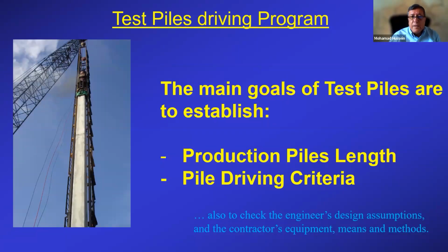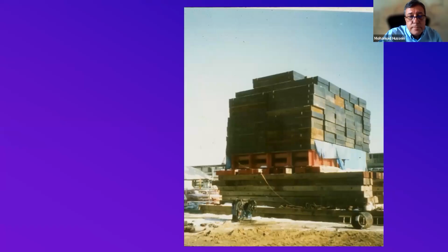We typically do that with a test pile program. So the main goals of a test pile program are to establish production piles length and pile driving criteria. It's also used to check the engineer's design assumptions and the contractor's equipment, means, and methods.